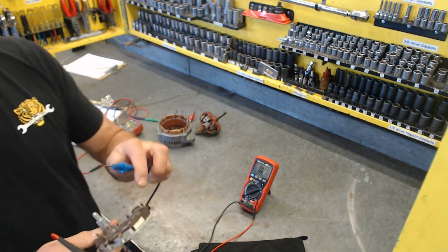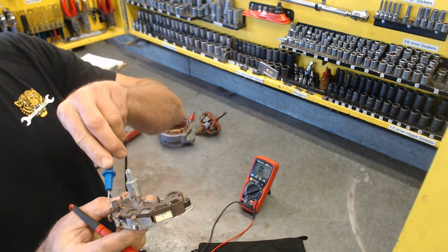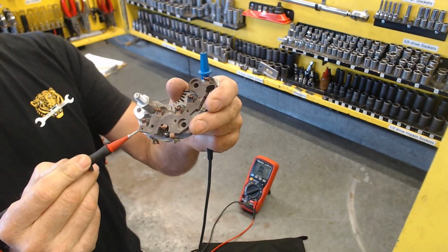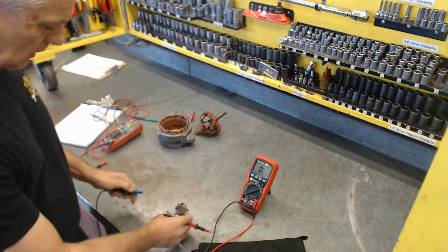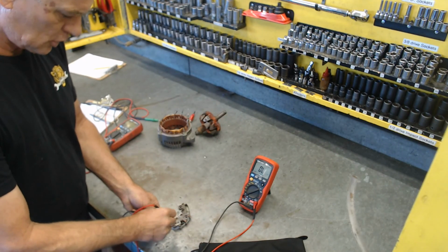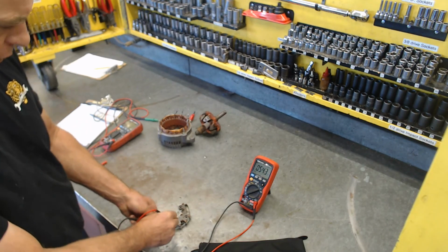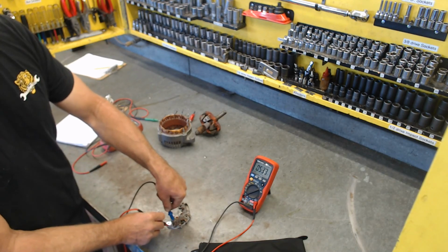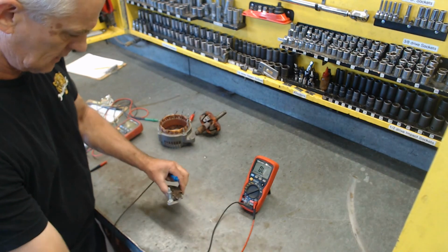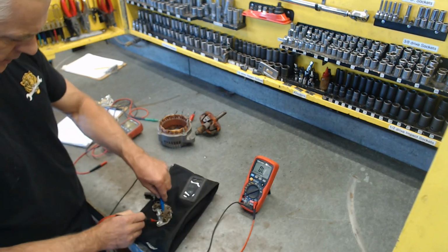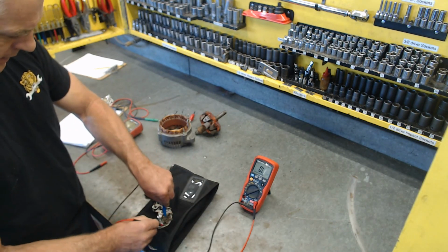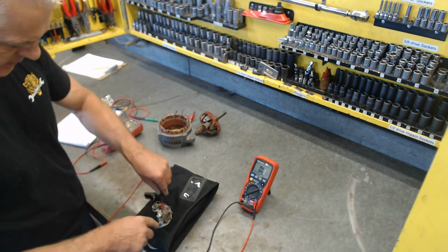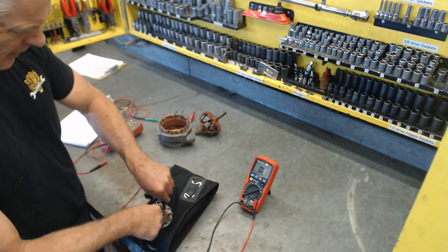So I'm going to touch this from this diode to the plate. Let me do that again. From this diode here to the plate down here, and then I reverse the leads. And what I should get is about a 1/2 volt in one direction, and when I reverse the leads and go the opposite way, I should get OL. Now, part of the problem is I have to make sure I'm insulated here. So I go on this guy here, and I get about a 1/2 volt, and then I swap my leads here and go there, and I get OL.